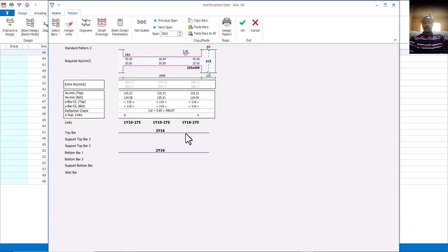If it's less than 20, what does it mean? It means that your quartz aggregate, which some people call stones, that is 20 mm, will not be able to pass through. So the only thing that will pass through is just your mortar, which is not healthy for the structure. Is that okay? So even though this place is showing red, and the red is not less than 20, no problem. Your structure is still very okay, because this place is only talking about the spacing between your reinforcement. Even though you're having a 21 red, 22 red, 25 red, 30 red, no problem.